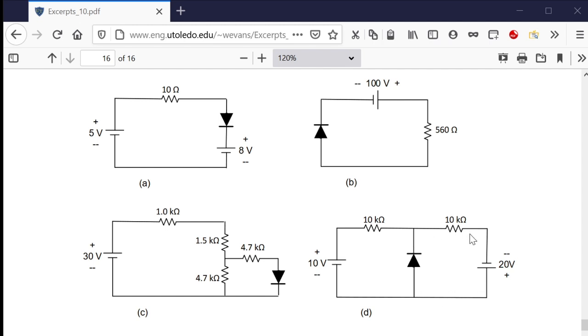So this one is going to dominate, and this one is not going to dominate. So we would actually be pushing with 10 volts out of this 20, and 10 volts would be fighting this 10 volts over here. So is 10 volts in this direction enough to turn this on? Oh, you betcha. So the voltage across the diode is plus on the bottom, 0.7, minus on the top.